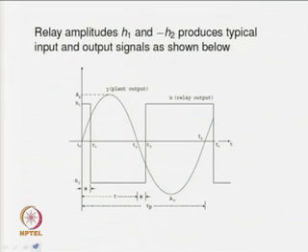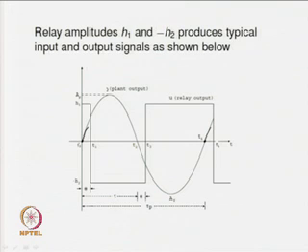You see that we have got a positive going output at time t equal to θ. Similarly, you must have a positive going output after time t equal to T4, then only there will be a sustained oscillatory output, or the output will repeat itself after every period. So, for periodicity of the output, it is a must that whatever state you have at time t equal to T0, you must get the same state at time t equal to T4.